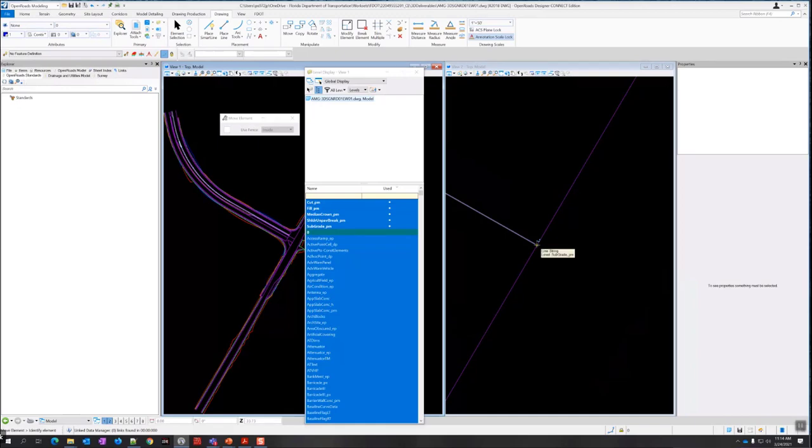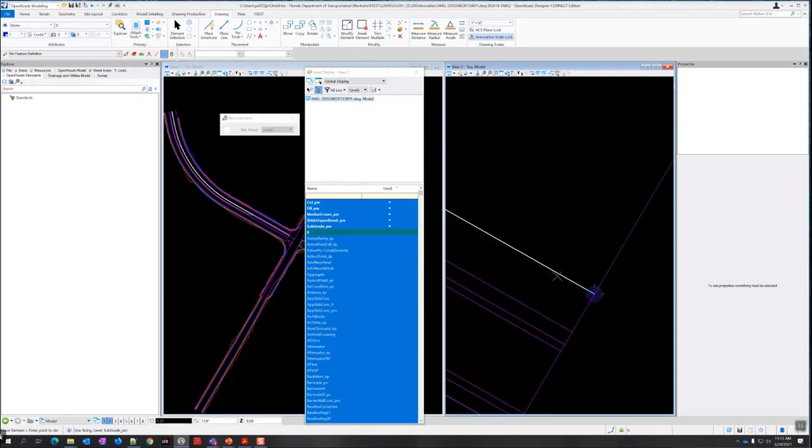So I'm going to hope it's selecting the one on top. And I really just need to move it over this way without changing it this direction. So if you use the RQ command, you can rotate to line up with the element, to rotate AccuDraw.